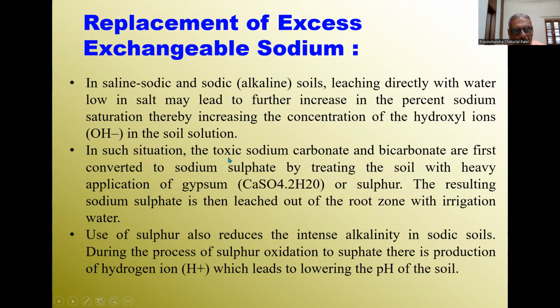In such a situation, the toxic sodium carbonate and bicarbonate are first converted to sodium sulfate by treating the soil with a heavy application of gypsum. When we add gypsum, calcium sulfate, sodium is replaced by calcium, so the soil becomes calcium clay. The resulting sodium sulfate is then leached out of the root zone with the irrigation water.